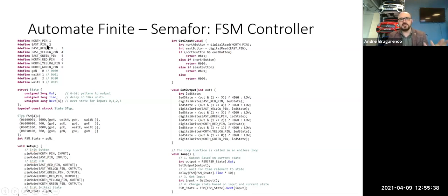The pins are detection sensors, detectors, let's say some proximity sensor, or some infrared detector, depending. We have the first two pins. After that, we will connect the traffic lights, the east traffic light on 3, 4, 5, and the north traffic light on 6, 7, 8. It could be configurable, but we can do it like this.